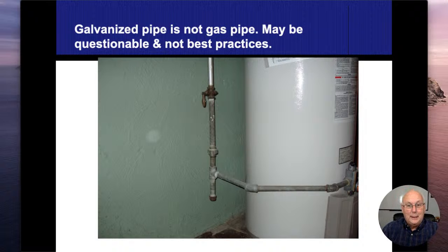Now, I do know there's a lot of suburbs in our area that do city inspections when there's real estate transfers. North Lake actually came to mind, and I don't even know if they still do this or not, but North Lake has it in their transfer protocols that all gas pipes have to be black pipe. All right. Now, I interpret that as black iron as the material, but their interpretation is color coding.